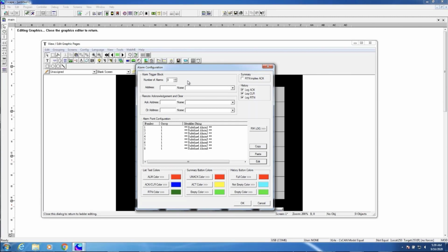So in this case, I'm just using the traditional register-based ladder. I'm going to go ahead and use internal non-retentive bits for my alarm status. I could use retentive bits. I could use registers. I have my choice. So in this case, I'm going to go ahead and assign T1025. Notice I used an address that is on a word boundary. So T1, T17, T33, etc. Those are word boundaries, and T25 is as well.